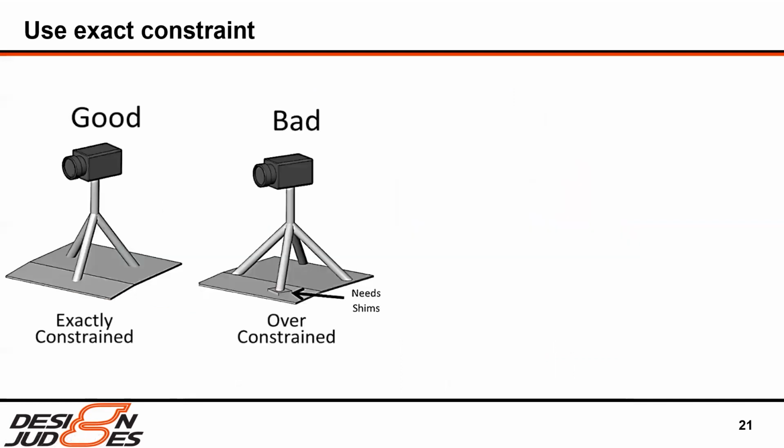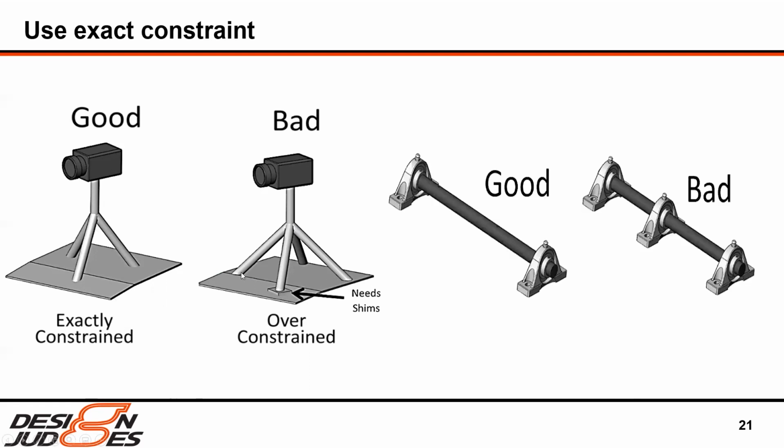Another common example is, if you wanted to make some instrumentation that could hold a tight position for long periods of time, or you wanted to make some mover that had to go over uneven surfaces, then I would use 3 legs. So 3 legs, for example, on the surface will always sit and won't rock. Whereas if you have 4 legs, it's going to be over constrained. It can sit flush on these 3, and then to get the 4th leg not to rock, you'd need some shims.